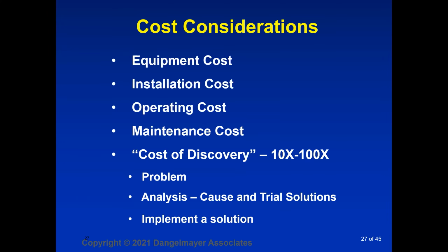Operating cost, very low. For ionizers, the power consumption when they're operating is very low, unless, again, you have heaters, in which case it will go up. Maintenance costs, you do have to do maintenance. Someone has to go out there and clean the emitter points periodically and check the balance of the ionizer. That's a cost that you need to be concerned about. So you have 4 different costs here that you need to add up to determine whether the presence of an ionizer is cost effective.